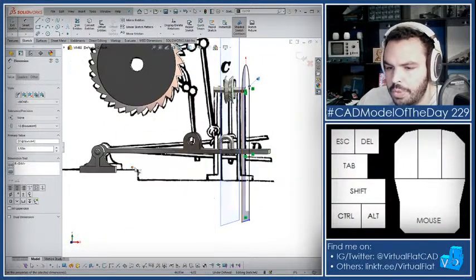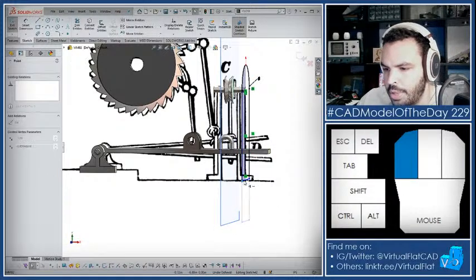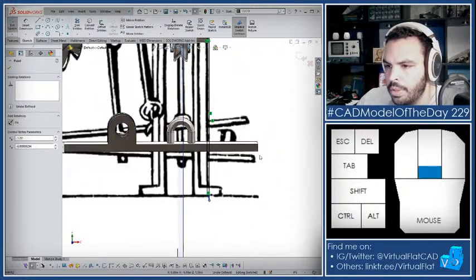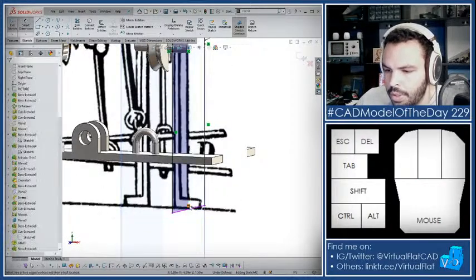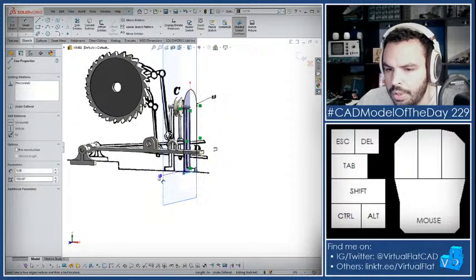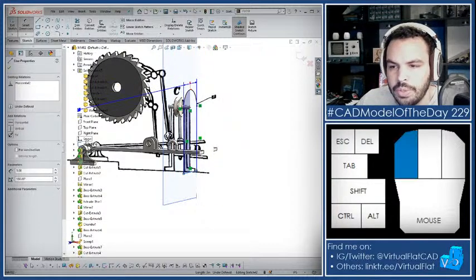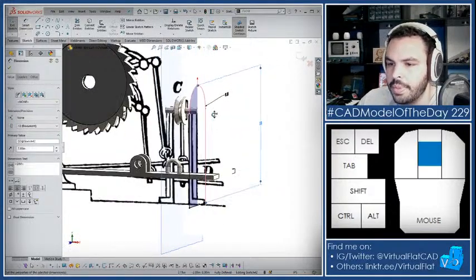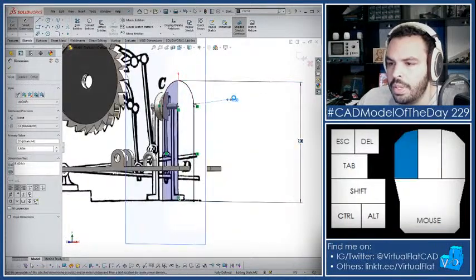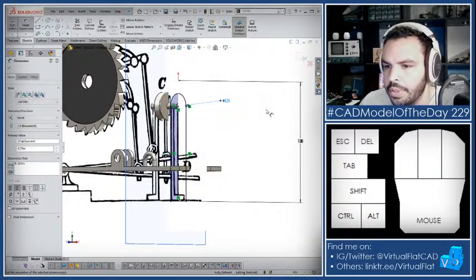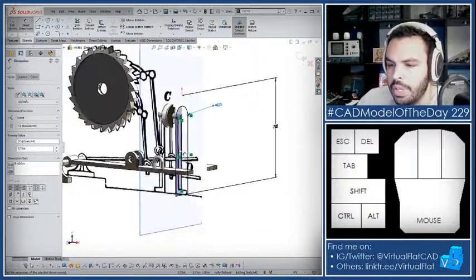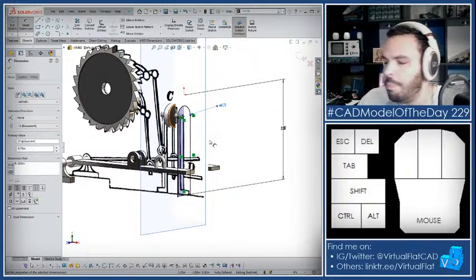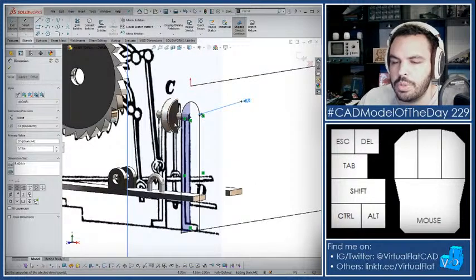Yeah, and this step height isn't really defined, so I'm going to have to do that on my own. And say, oop, no, that's right. From here, let's just do it to the origin. Again, one of those things. I can just select it from here. Oh, that really wants to be 7. Let's do that. And actually, I want to make this way smaller. There you go. Yeah, the other tricky part is I don't want this thing to be so big that it blocks the pulley and then it's harder to see what's going on.